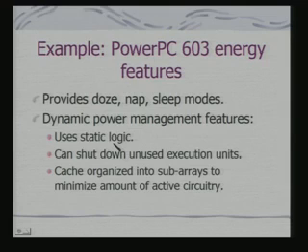It uses static logic and not really dynamic logic. It can shut down unused execution units; that provision is provided explicitly. And the cache is organized into sub arrays to minimize the amount of active circuitry when a cache access is taking place. In fact, this point we shall discuss when we look at the memory architectures for power optimization.